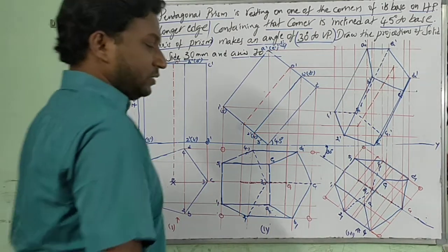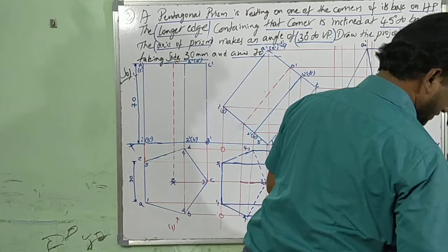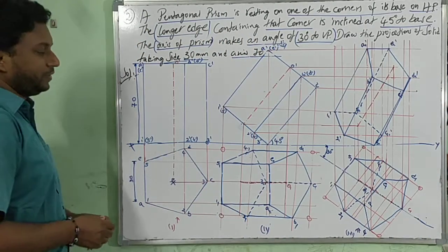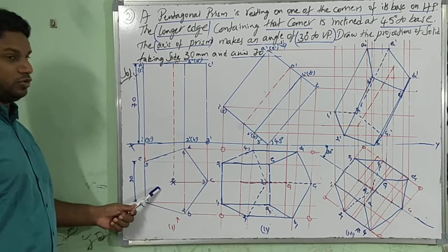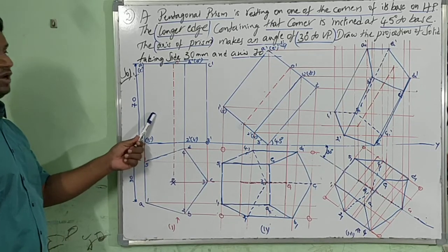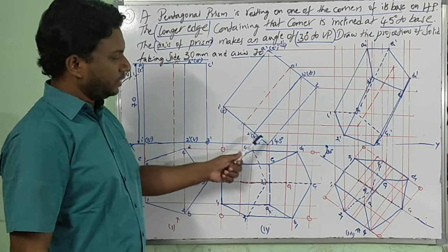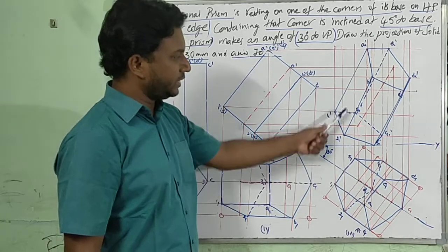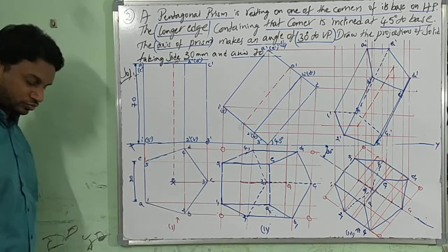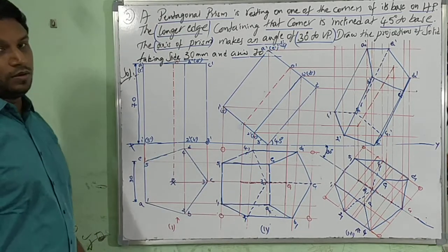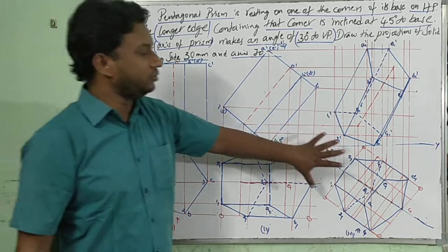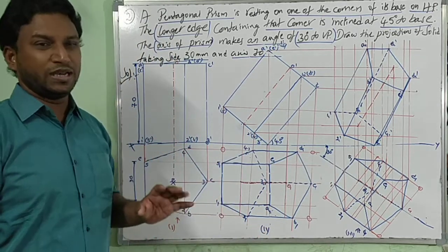Hope you all understand. Don't think it is a lengthy problem or a tough problem. Please do consider the first position top view true shape and its respective front view. Second position, 45 degrees inclination, top view. Third position, 30 degrees, and its front view. I know that you will be very clear up to here. Now the third position is a little bit confusing.